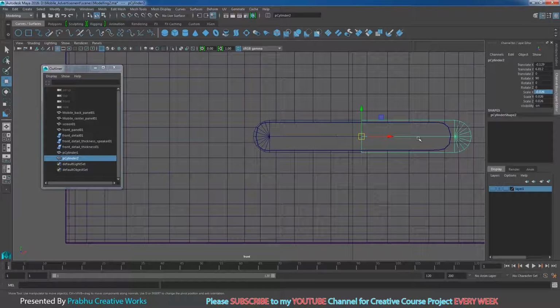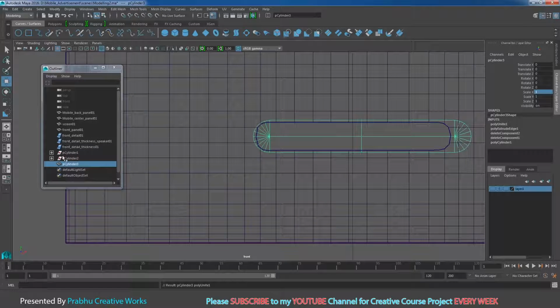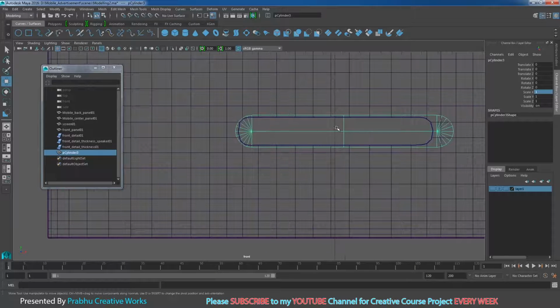So select this one and shift select this one and go to mesh and choose combine. So now we have a lot of history. So I will select this object, go to edit, delete by type and choose history. So our history will clear.